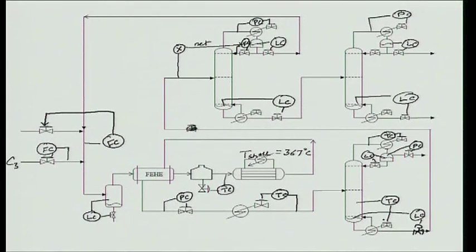I also, but you see, okay, on this column maybe I should change the colors, because on this column what do I say? Well, boil up needs to be max, okay. But I do not really have not done the optimization. So, conventionally what I would do is I will control a tray temperature and there will be a V1 max or V2, this is second column.